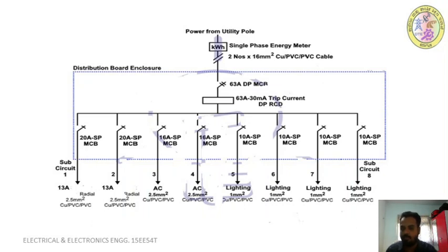Okay, four machines or motors you can call. Another four circuits we are using for lighting of the factory, right? And each individual machine is provided with MCBs and switches. Since it is a single phase supply we have taken, we are using DP switches, and one more main DP switch which you have placed in the main board itself.